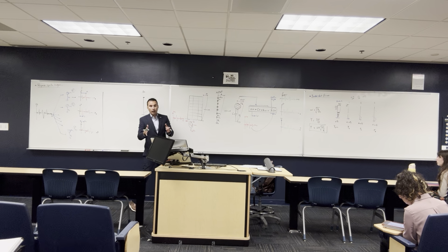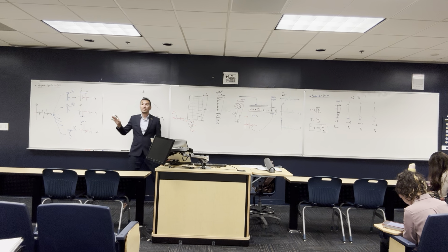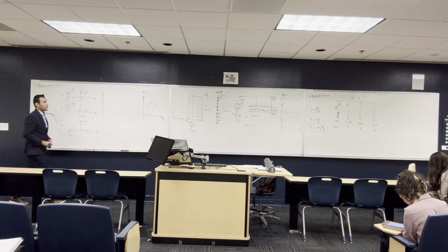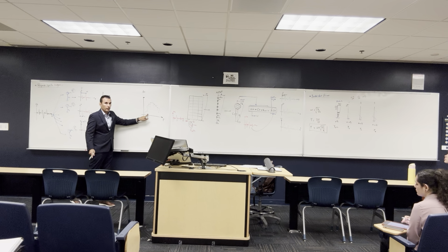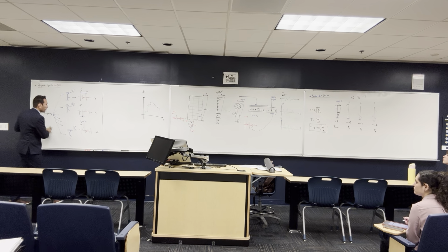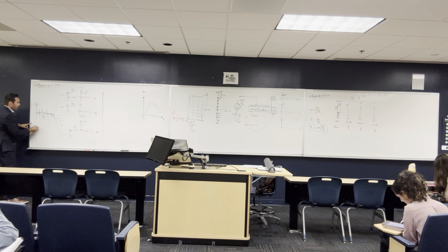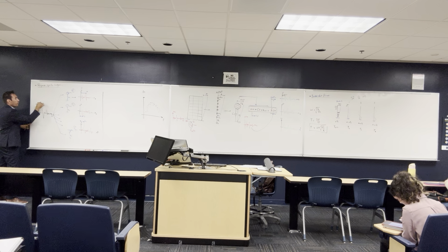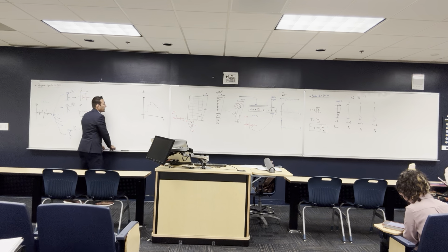So they have a suite of earthquakes, like maybe 10 or 15 or 20, and they did the same process for all the buildings again. The thing is, this curve is for just one earthquake. One earthquake was applied to a spectrum of buildings. They did the same process and brought another earthquake, and another one, and they did the same process again. Every earthquake that you use is going to give you another curve.